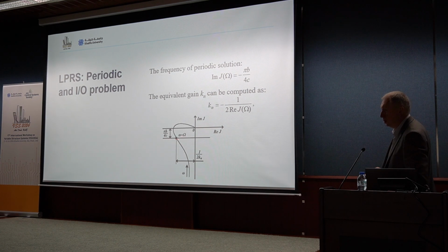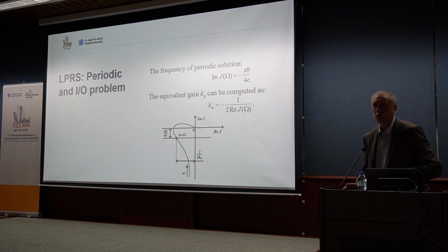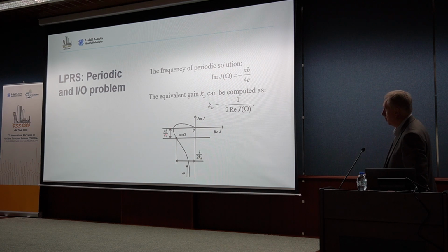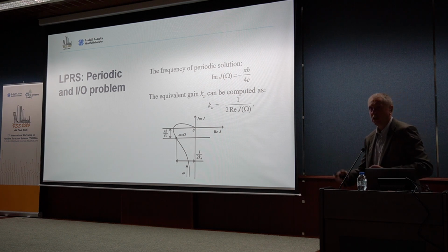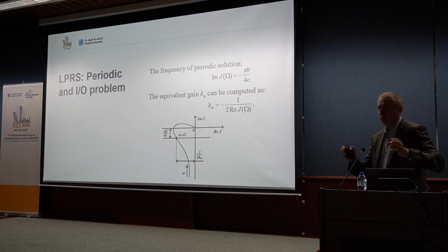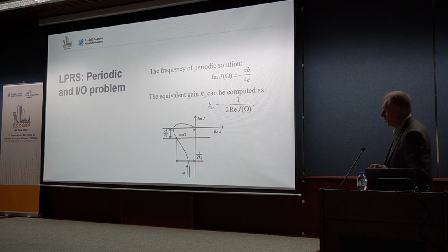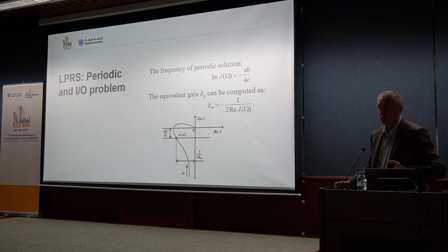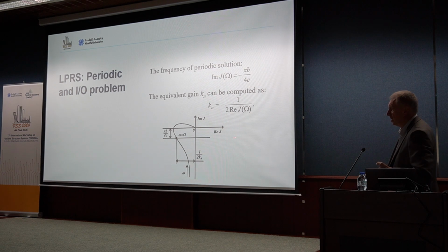This will be, it's not a describing function anymore, but a similar condition. I would say this line defines a switching condition now. Also pi b over 4c, because it was designed as an imitation of this describing function and harmonic balance principle. So LPRS is a replacement of the Nyquist plot, and all the rest remains the same.